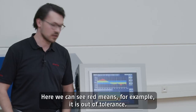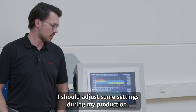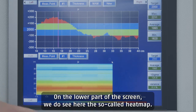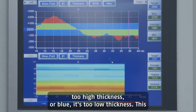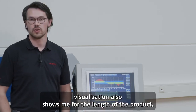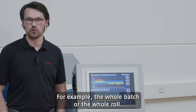Here we can see red means, for example, it is out of tolerance. I should adjust some settings during my production. On the lower part of the screen, we see the so-called heat map, also visualized with colors. Red is too high thickness, and blue is too low thickness. This visualization also shows me the length of the product, for example, the whole batch or the whole roll.